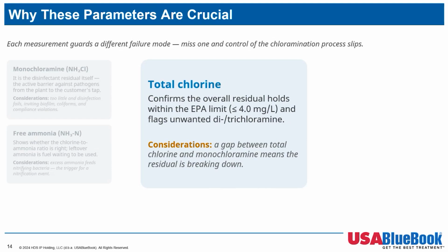Total chlorine is your compliance number. And with monochloramine present, it's the one you report, not free chlorine. But it's also a diagnostic. If total chlorine and monochloramine start separating, that gap is your residual breaking down into something you don't want.